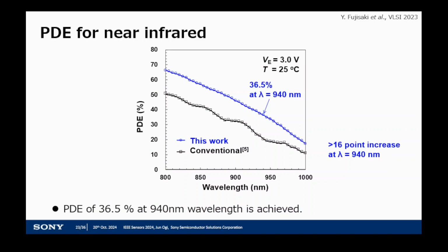And as a result, the developed structure has achieved 36.5% at 940 nanometer wavelength with a 6 micrometer pitch pixel. This enhanced PDE should contribute to improving depth sensing performance in time-of-flight range image sensors.